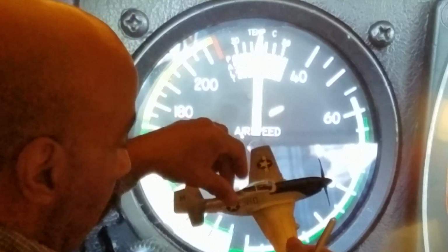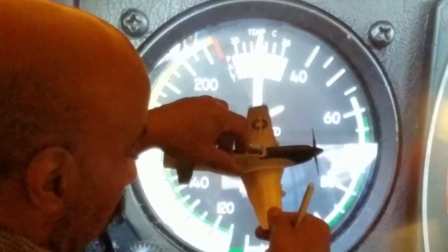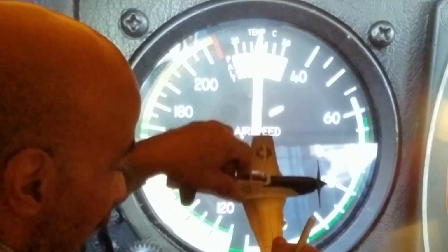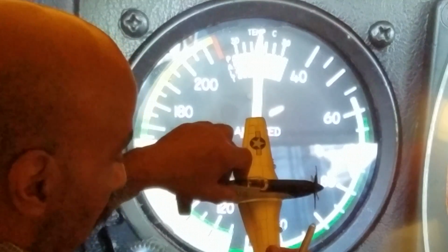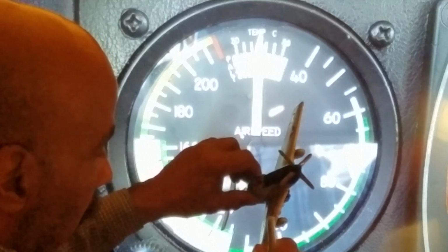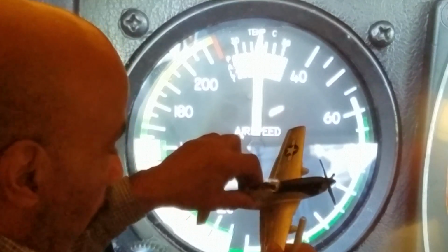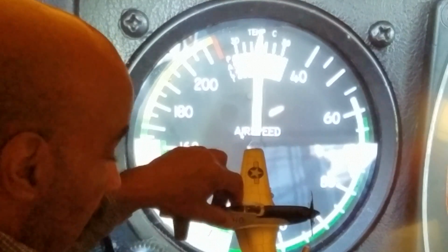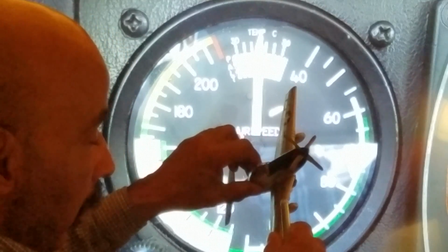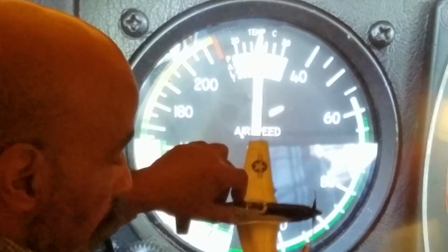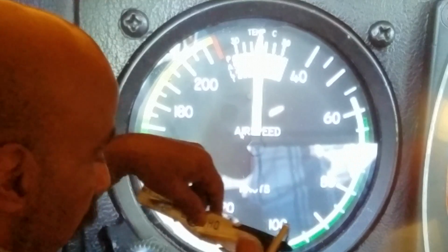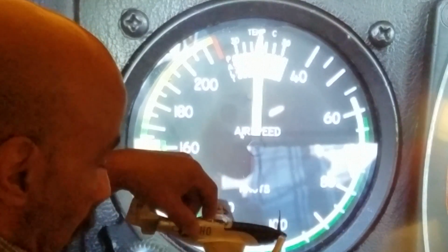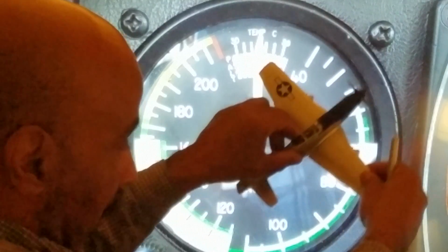An accelerated stall is basically yanking on the flight controls, usually in a bank, usually in a turn, and you're pulling the nose up. That means you have pulled back on the control yoke or stick, and you're trying to climb. In this case, you have a wing low, so climbing is moving in this direction rather than up, although you can climb like that.